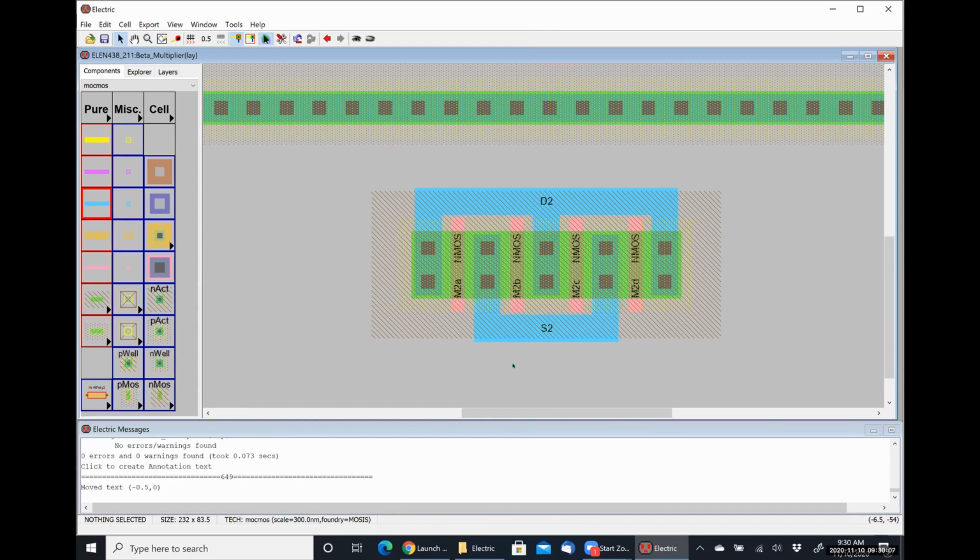There we go. It's going to have to jump over a guard ring, so I'm going to need to do something similar to what I did with that PMOS transistor up top, I think. The drain source is going to be tied to our resistor, and the gate voltage is going to be tied to V bias P.